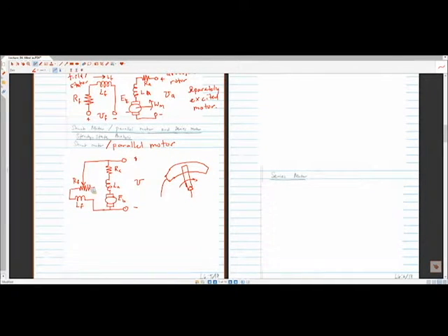So you have some sort of contact point, and you can move this left or right to get higher or lower resistance. What that does is it allows you, with a single voltage source, to independently change the flux coming from the field. Voltage sources are fairly expensive. Variable resistors are pennies. So with a pretty inexpensive solution, a really simple potentiometer, you can maintain a constant voltage if you want.